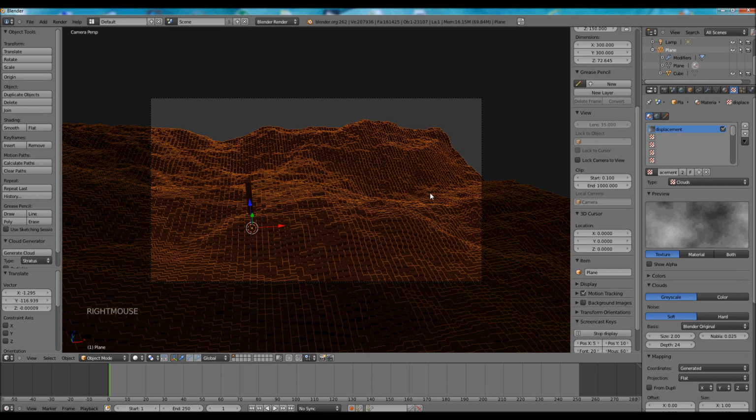And then, sorry, right click on the plane again, and let's keyframe the size a little bit. Make sure that you move your cursor over the field, then press I. You can also right click and then choose insert keyframe.